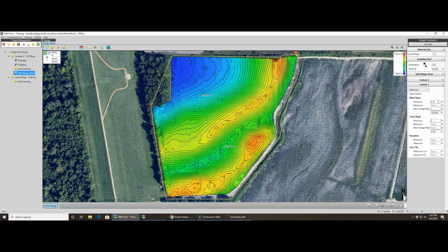This is the smoothing factor. The smoothing factor, 1 over 10 is the least smoothing, and 1 over 300 is the most smoothing. Downhill direction, 1 over 100 generally works in most cases. I rarely move that off of 100 in a downhill scenario. Our cross slope is a different story. Cross slope will be 1 over 300 about all the time. Okay. Cross slope, minimum and maximum.